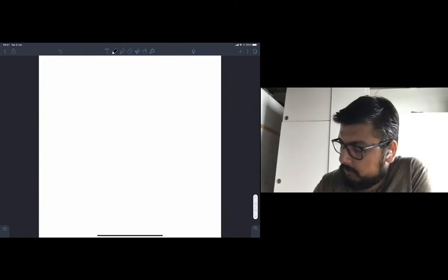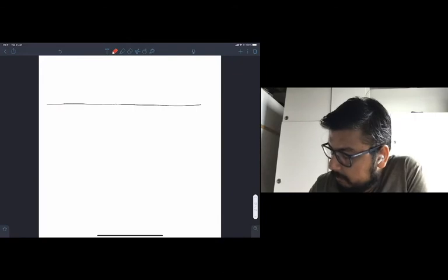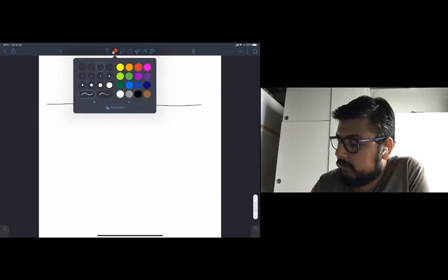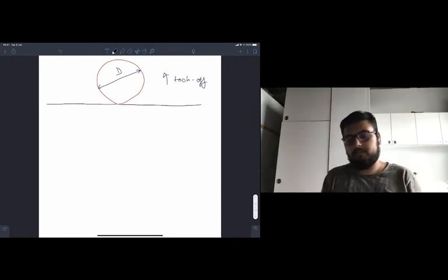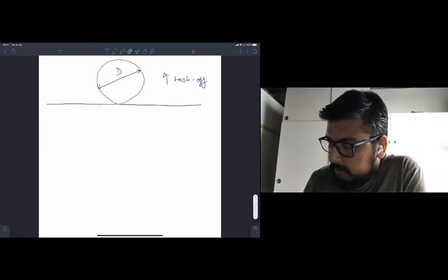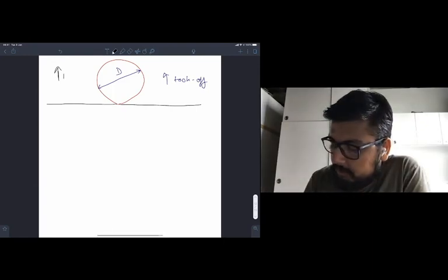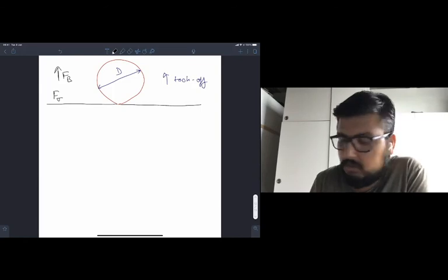So what we saw in the video was an orifice and a bubble coming out of this orifice, and at some certain diameter d, this bubble took off. Can we predict this diameter? So to predict the diameter, we need to know the relevant forces in the system. The most relevant force, the one which you can easily recognize, is the buoyancy. And then of course there's surface tension force. And these two are the competing forces in the system.